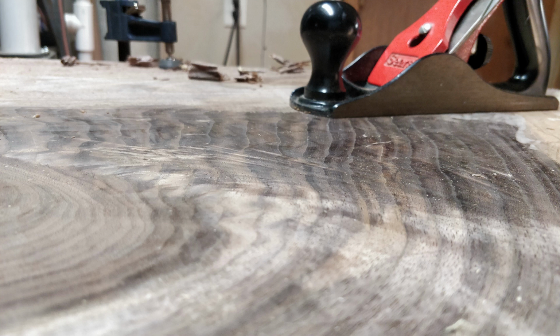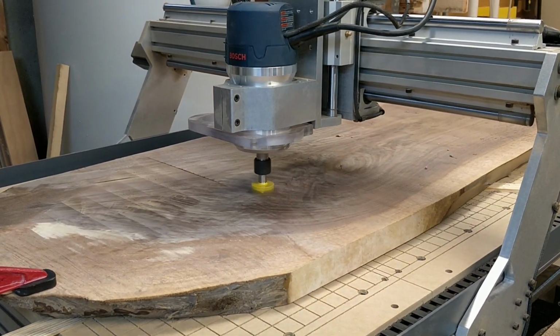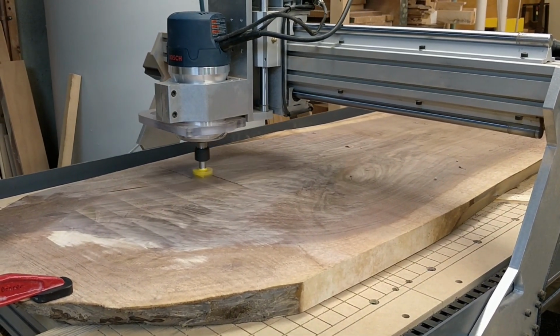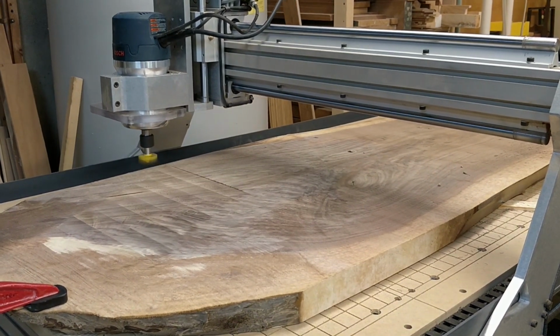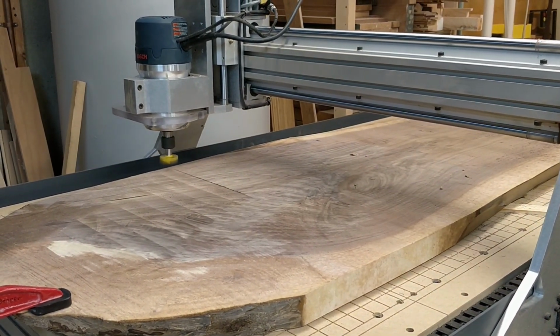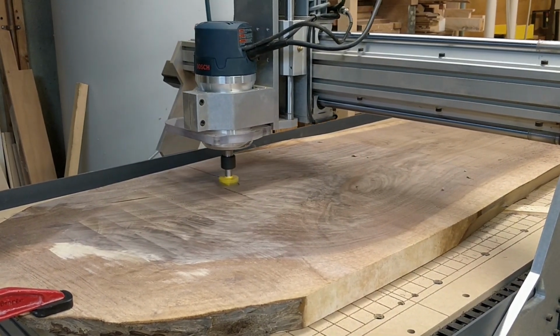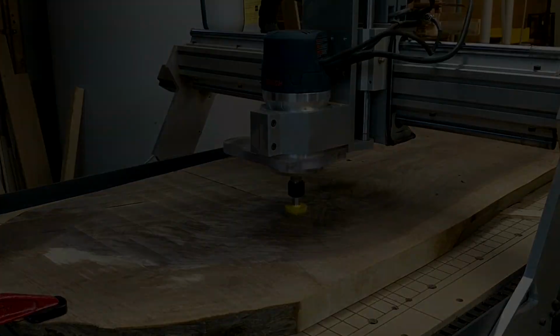more to go. We moved on and started using the CNC machine for this. It made life a lot easier. We started with the bottom and made that flat and then moved on to the top. The top did pretty well. We used both vertical and horizontal paths in order to get there. We took off a 16th of an inch at the beginning and then moved down to a 32nd. It required a couple hours of machining time to do this.